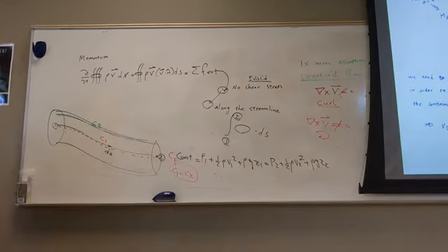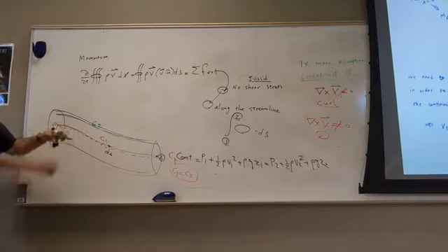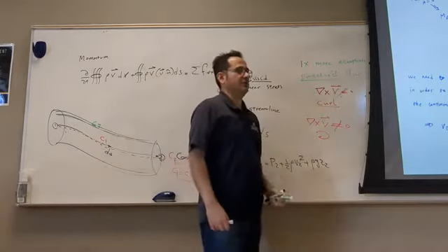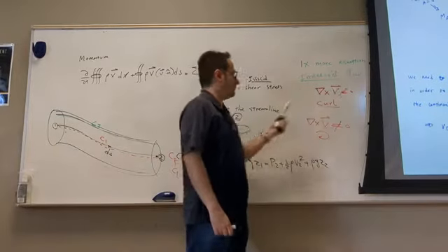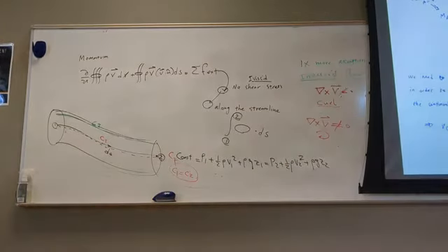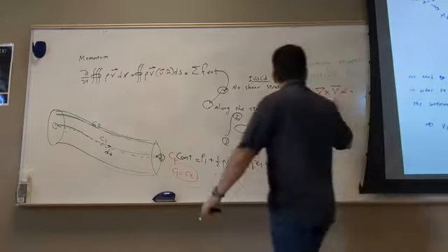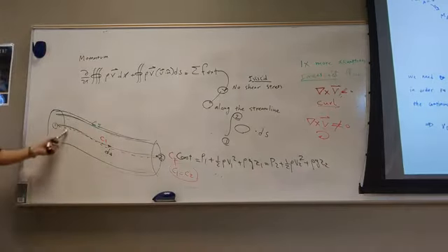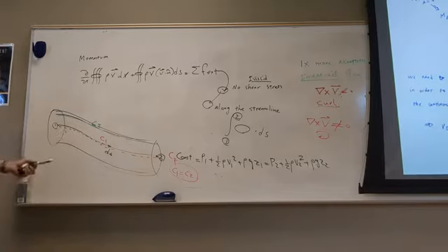That means, this is interesting. The constant of Bernoulli is the same everywhere in the field if the field is irrotational. But this is one more assumption, right? The basic assumption is implicit. When I gave this problem to you, I just said it's implicit. But if you make one more assumption, that it's irrotational, you can say this constant is equal to the same value everywhere. What does it mean?